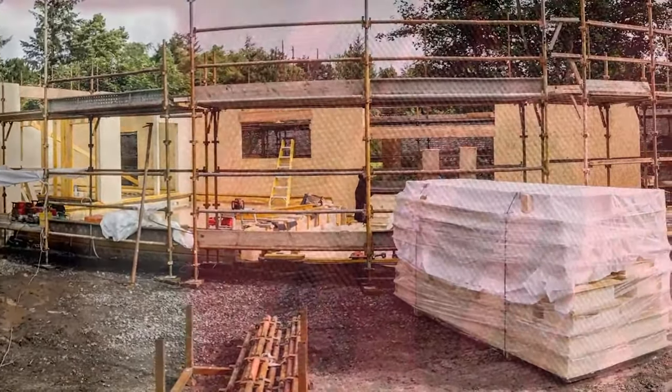The roof joints and structural decking are therefore kept well above the dew point temperature, making this kind of roof far less prone to condensation issues. Because the insulation is usually unbridged, they also maximise the thermal insulation performance.